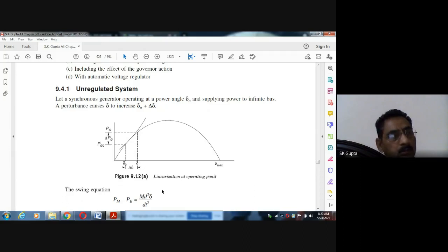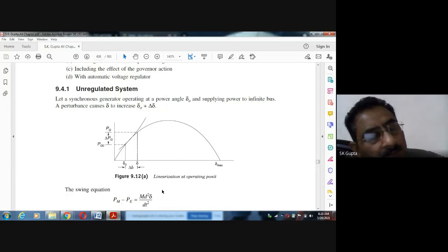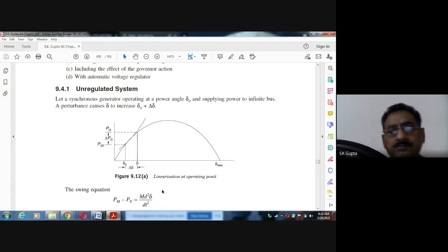During a disturbance, the rotor and rotating flux are not synchronized to each other, which means there is relative motion between the two. Because of the relative motion, there is induced EMF in the damping winding, not in the field winding, because damping windings are short-circuited windings. During that time it behaves as an induction motor and tries to damp out the system. It opposes the cause by which it is produced, and accordingly damps out the system.